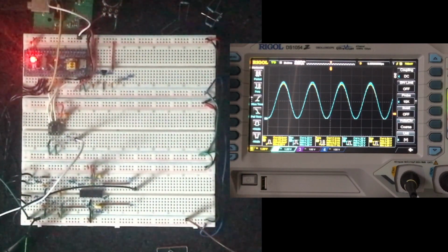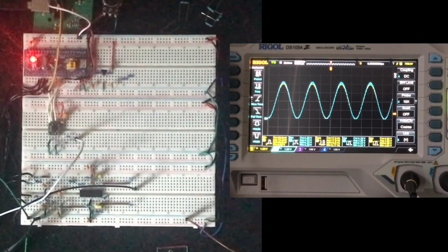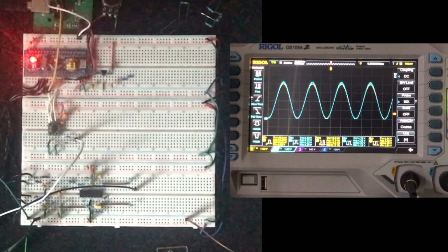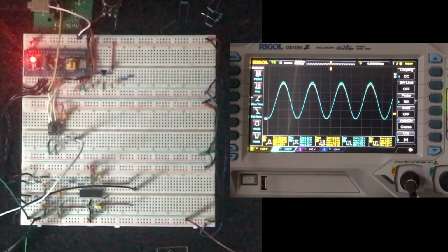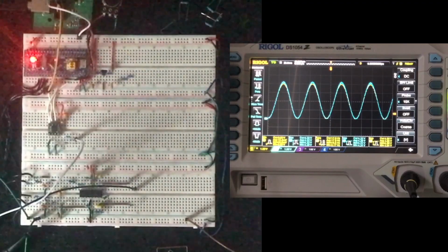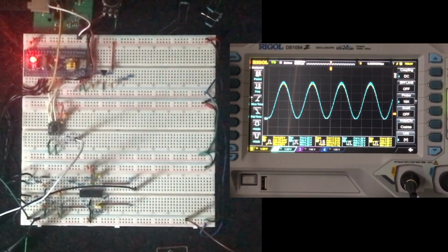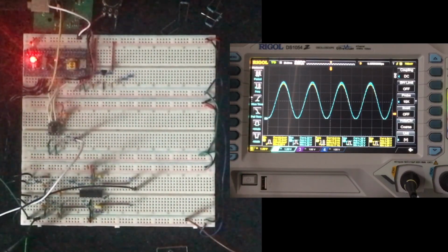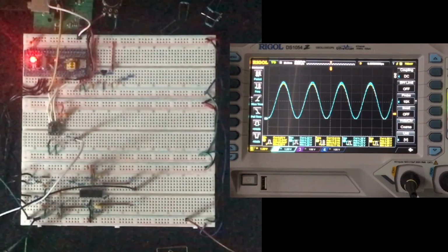Okay, so that's different than the bit rate. Bit rate is how many values you can have representing a particular sample. But sample rate is how many samples you can have over time. So say, for example, you have 44.1 kilohertz, which is CD quality, right? Now, CD quality is also 16 bits. So you have 16 bits of information. Over here, we have 12 bits, which is lower resolution.